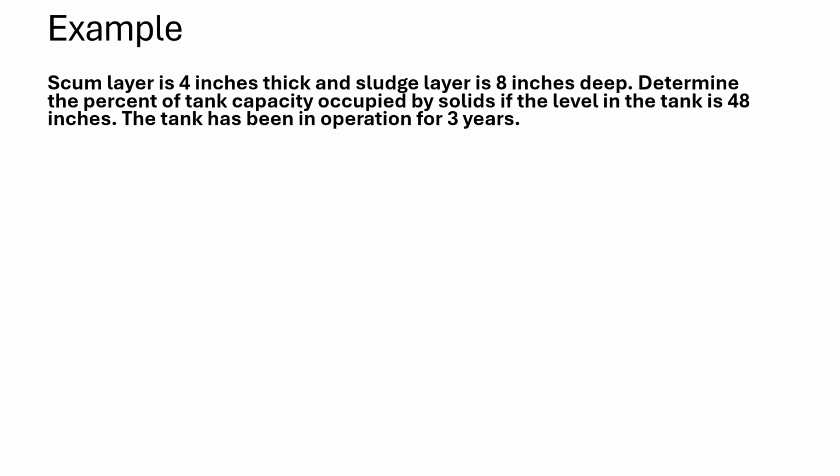And consider also that the tank has been in operation for 3 years. So to do the calculation, first of all, we're going to add our solids levels together. 4 inches of scum plus 8 inches of sludge equals 12 inches total of solids.